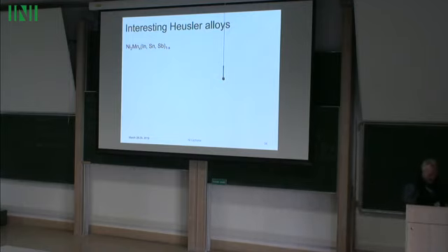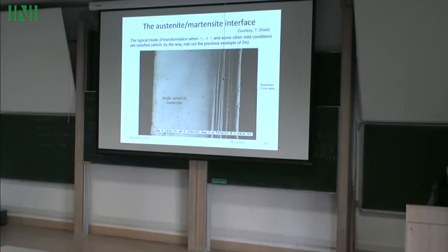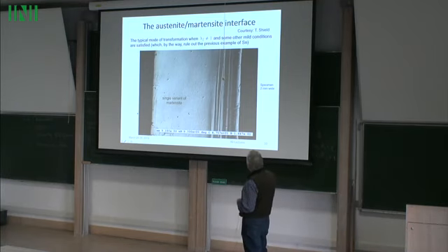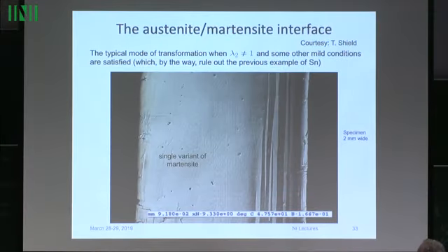Okay. We had it's like a single variant of martensite, but on the right hand side... Okay, so we weren't completely successful in detwinning it. This is a single crystal of one variant of martensite, and in fact it's twinned. There's a rank 1 connection with another variant. So this part is messed up with other variants, but anyway, most of it is single variant. It's just an incomplete detwinning, but it was mostly that variant.